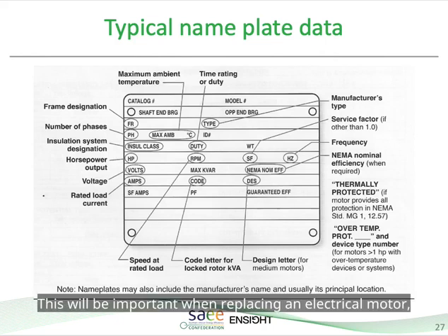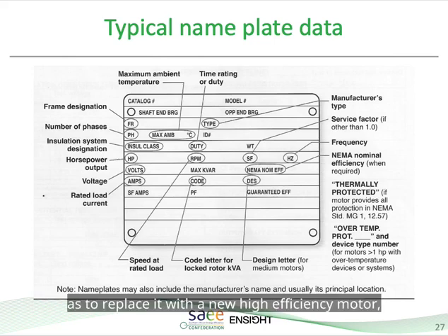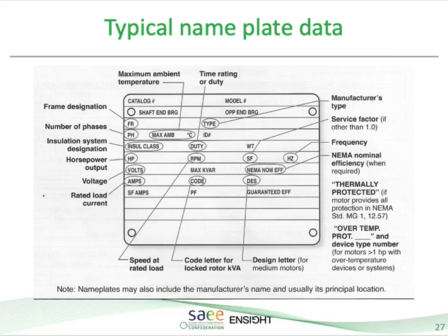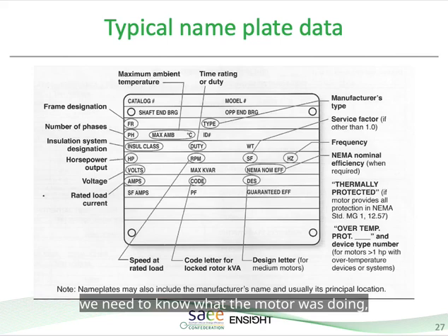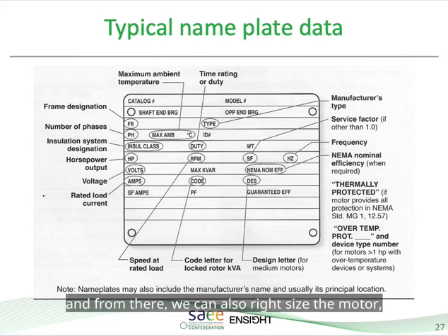This will be important when replacing an electrical motor with a new higher efficiency motor. We need to know what the motor was doing, and from there we can also right size the motor. We can determine if the motor was oversized or undersized for the application.